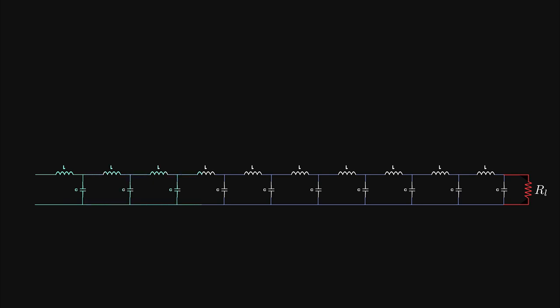The voltage at the input of the line is 200 millivolts from voltage division; let's call it V1, and it injects constant current during that trip, irrespective of the kind of termination. When the signal finally reaches the end of the transmission line, the voltage at the end point becomes V2, depending on the value of the termination resistance, so that the ratio of the voltage over the current equals the load resistance, and the current drawn by the load resistance settles at V2 over RL.